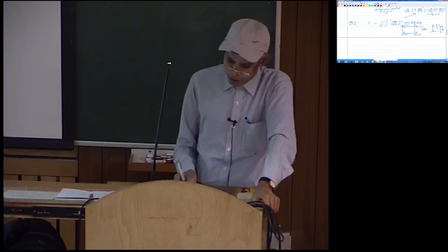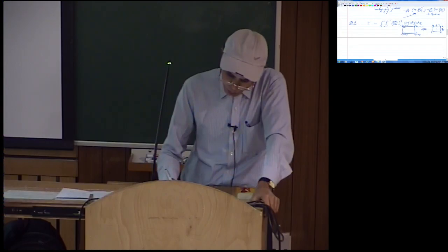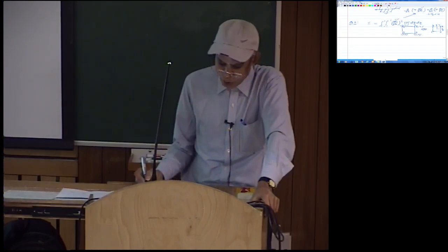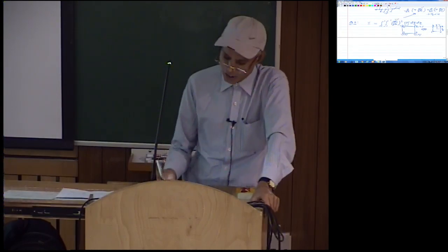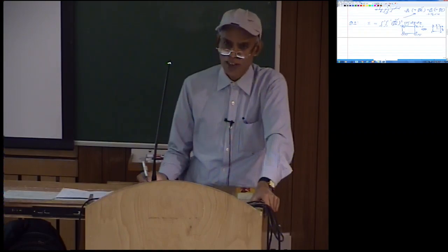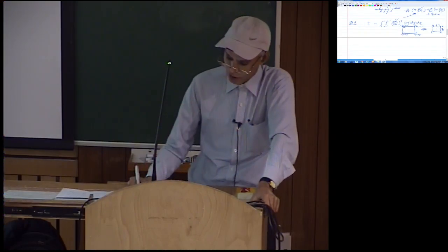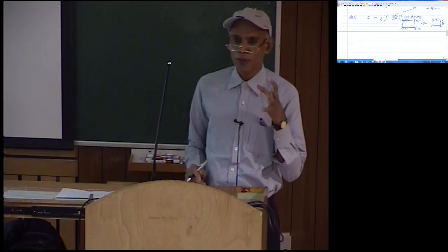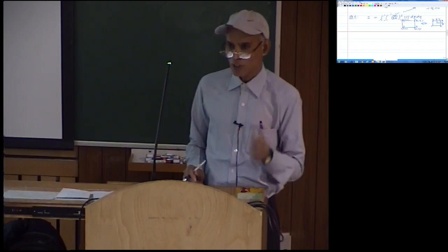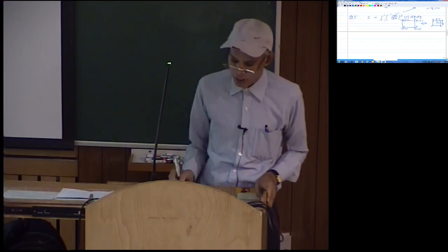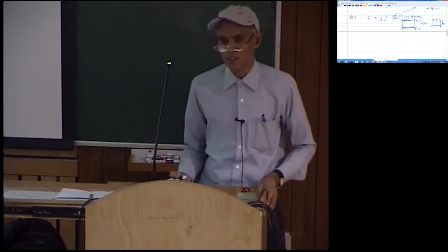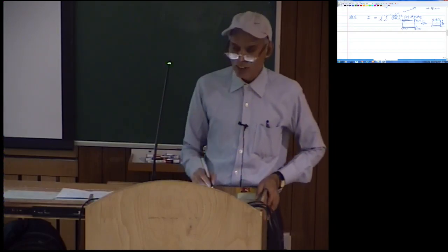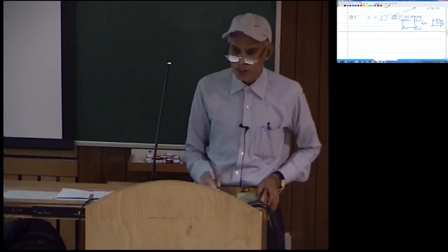Obviously, because you want to evaluate this integral, first you have to have the expression for ∂N1/∂x in terms of xi and eta, the expression for J in terms of xi and eta, and then use the numerical integration. To get J and even ∂N1/∂x, you need to evaluate your Jacobian, then the inverse of the Jacobian, then express your ∂N1/∂x, and then do the numerical integration. So that is what was expected. I think this is straightforward, you can look at the solution.